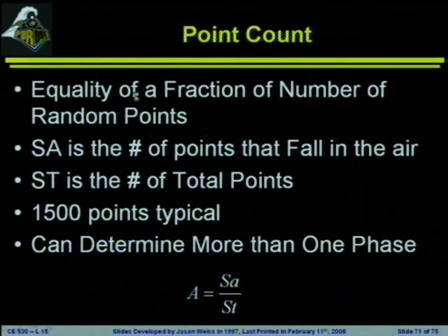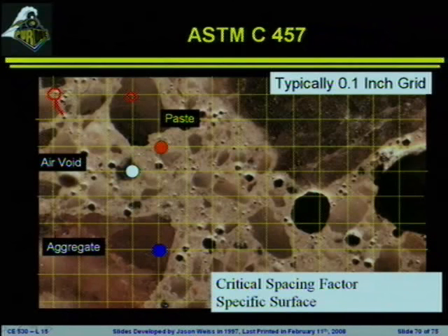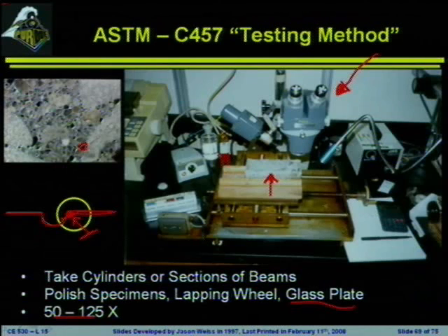system. Now, unlike what I've shown here where we actually have the grid placed across the top of the system, in the actual test, the entire thing is on what's called a Rosiwal traveling table. So the microscope stays constant, and you're going to be moving the sample back and forth underneath it, with each turn of the table being usually about 1/10 of an inch of movement.